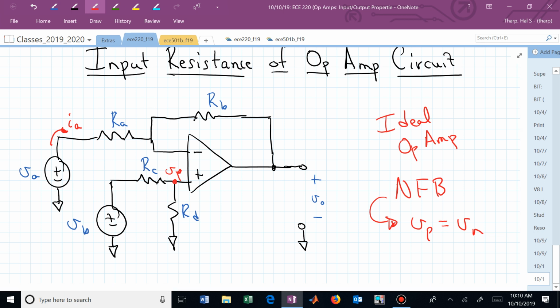It's not as neat as V sub P, is it? It's kind of splattered around. It's this big thing. That's now V sub N. It's a blob, but it's still there. Each of those wires are connected to the inverting pin of the op amp. And now with negative feedback, we're going to assume that we have a virtual short between those two. They're at the same voltage.